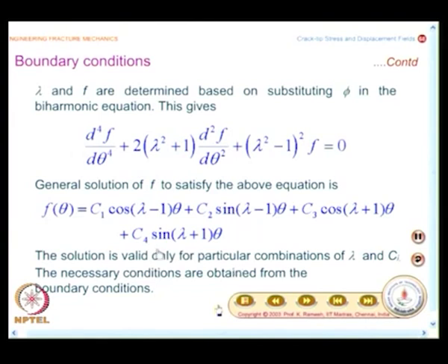And what we will have to do is, we have already looked at what is the meaning of sigma theta going to 0, what is the meaning of tau r theta going to 0. Now we will adopt that we have the function f of theta. So we look at f of theta as well as f prime theta, then you get the basic equations, from that you write the characteristic equation, find out the eigenvalues. That is how we are going to proceed. It is a very standard way of solving a system of equations, we are not doing anything new, but if you follow the procedure and have that in your notes, you will feel comfortable when you review it later that whatever you have done is mathematically rigorous.